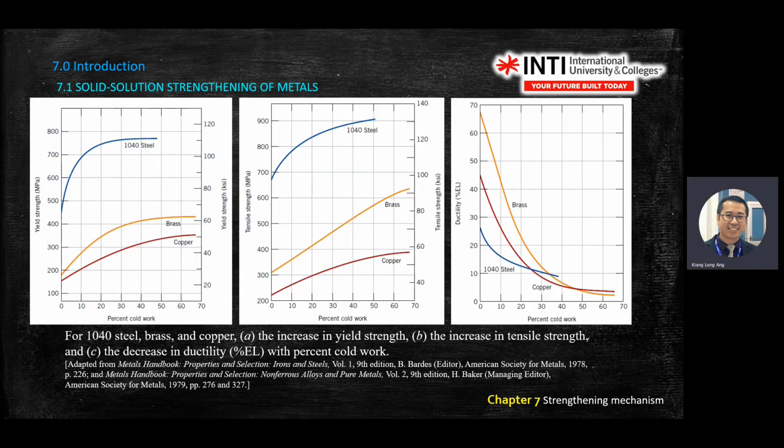So you have three graphs here. On the left, the y-axis is the yield strength again, and the right-hand side also uses strength, but imperial. For our module, we are only interested in SI units, so focus on the SI unit. It's not necessarily on the left. You need to read carefully, sometimes it's on the right-hand side. Percentage of cold work is on the x-axis.